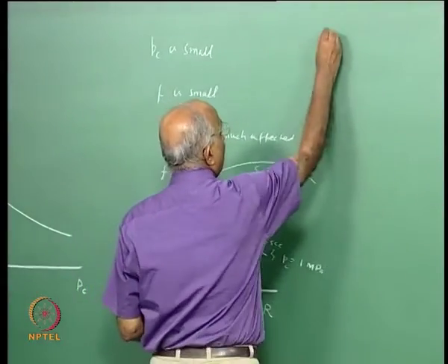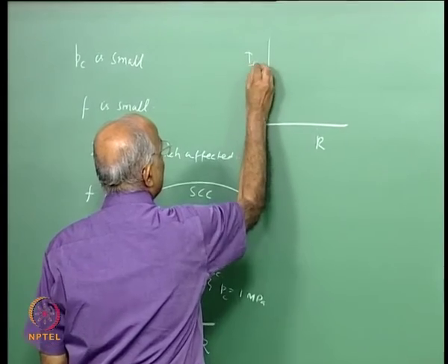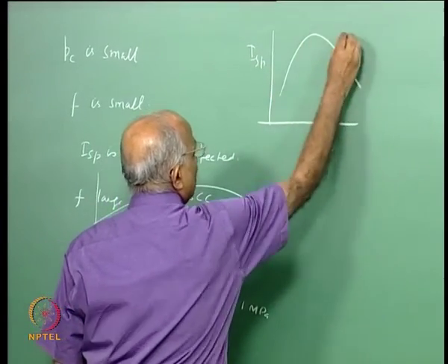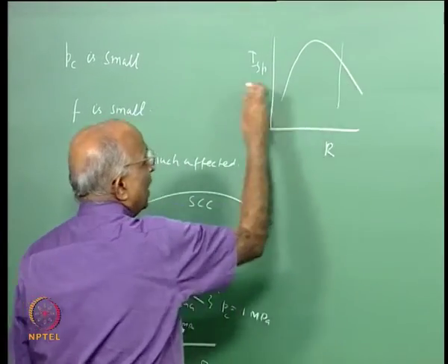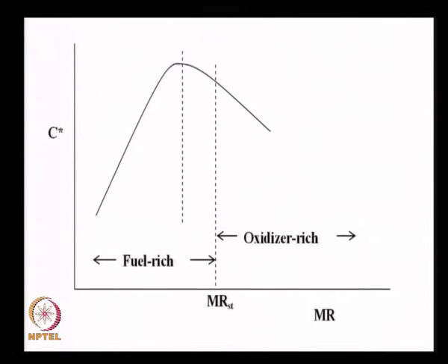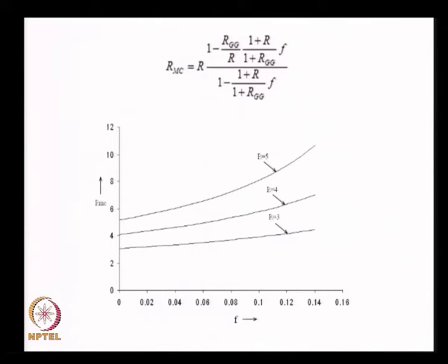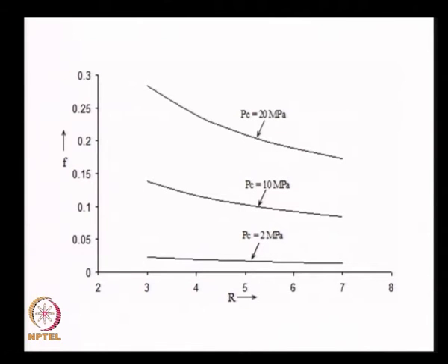In other words, what we just now told you was R versus the specific impulse or C star goes like this. We start operating at these low values, and that is why the specific impulse or equivalently C star or the total performance keeps falling. This is how we compare the different feed system cycles such as the gas generator cycle, the staged combustion cycle, the expander cycle, etc.